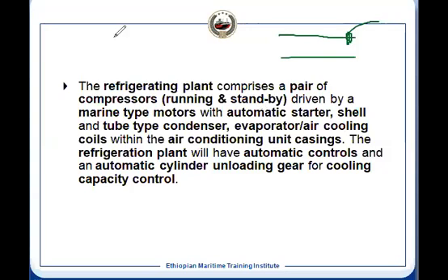In that case, we have the evaporator coil through which the refrigerant is passing at low pressure, and it gets evaporated, and when it is coming out, it is coming out from the flow. For example, this is the evaporator. So this will be at low pressure, and it is liquid with a very small quantity of vapor because of the thermostatic expansion valve and because of the flash evaporation. And then at the end, it will be 4 to 7 degrees